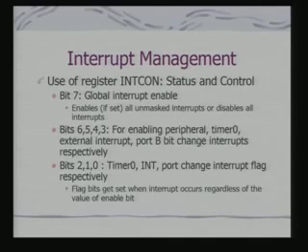When a vector interrupt occurs, the processor starts execution of the interrupt service routine from a fixed address. In fact, in PIC, we have only vector interrupts. The INTCON register is used basically for managing the majority of these interrupts. Also, there are other registers which are equally involved.